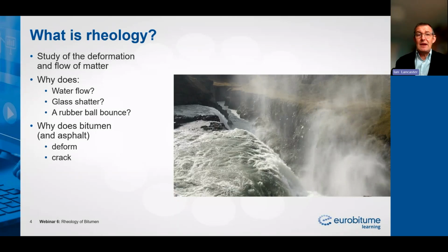So it explains why water flows, why glass shatters under the right conditions, and from our perspective, why does bitumen, in some circumstances, deform? Why does it do that? And in other circumstances, why does it crack? Well, rheology explains all of that, and we're going to come to the rheological testing in a moment.